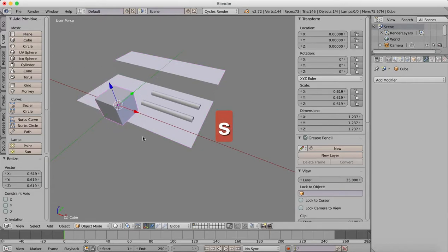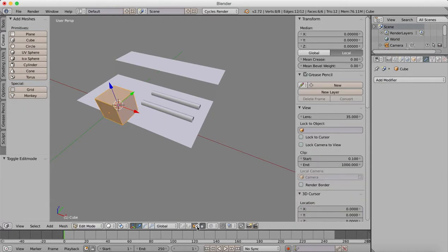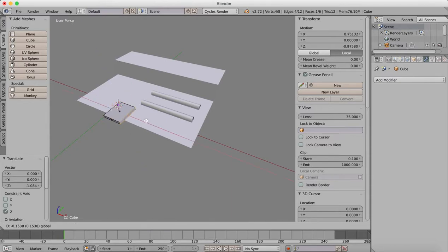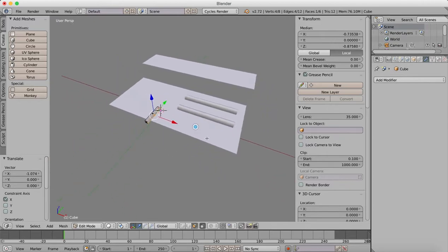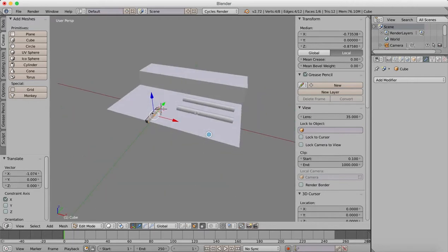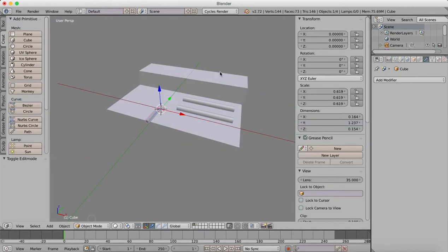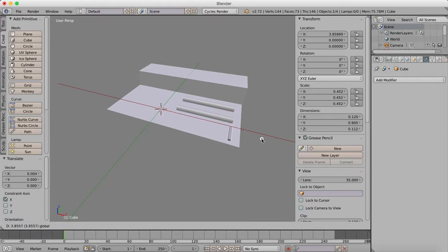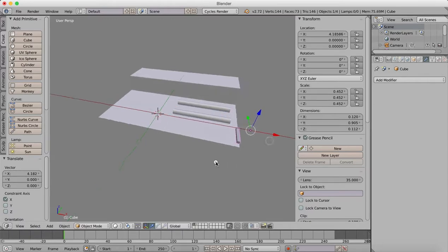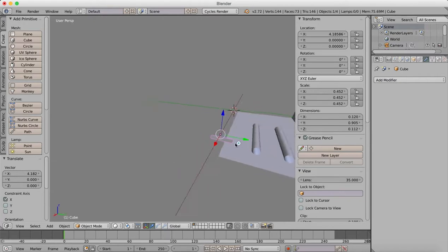And this cube here, we will jump into edit mode, select the top face, select our bottom face. I want to make it into a little kind of oblong metal bars. This is going to form our grid for the floor, so I'm just going to scale it down a little, move it forwards, so I want to align it up at the end there.